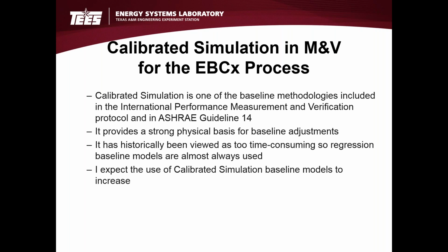The thing that I very much like about the use of calibrated simulation in this case is that it permits you to have a strong physical basis for adjusting your baseline if there are changes in anything like building schedule or the use of a particular portion of a building, or you end up changing out a piece of equipment in a small part of the building. All of these are things that the typical regression baselines are really incapable of dealing with. With calibrated simulation, you can handle them very readily.